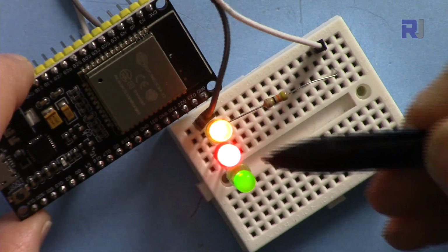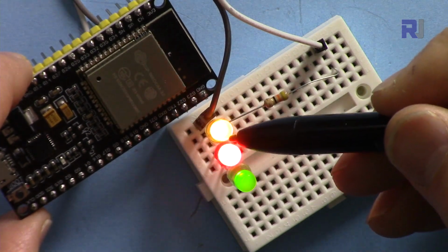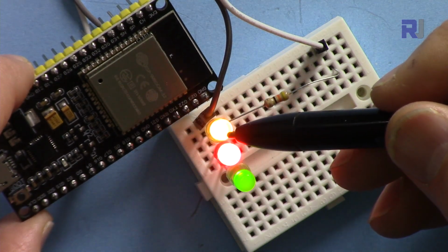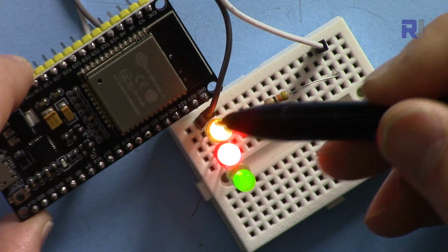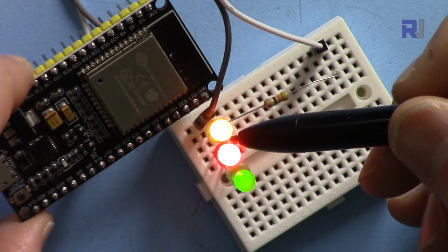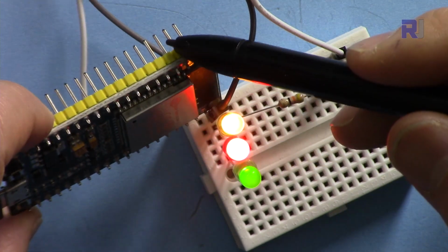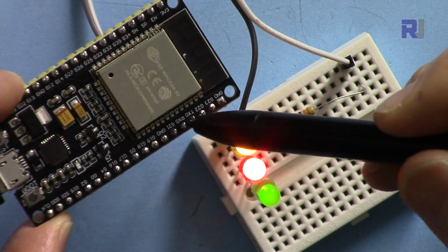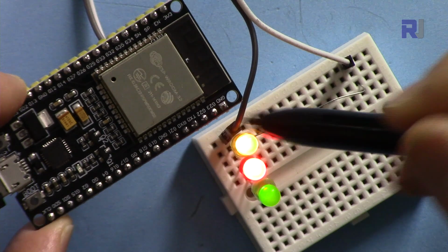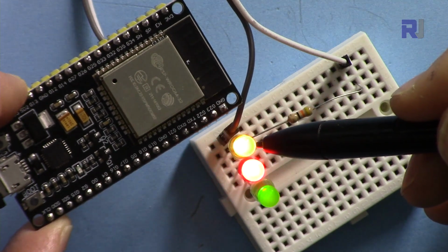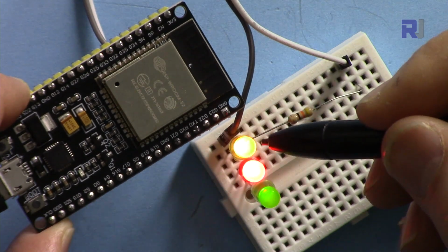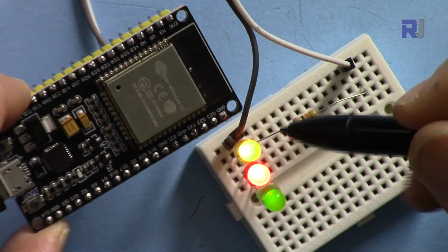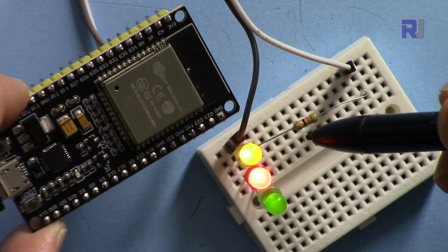Now each LED that you connect, depending on the characteristics, is generally about 2 volts, maybe 1.9 up to 2.1 volts, but on average we can say this is 2 volts, and the output from the ESP32 is always 3.3 volts. All these pins that are outputting are 3.3 volts. So if you connect an LED directly to 3.3 volts, it will get damaged. Sometimes immediately, sometimes within a few minutes or maximum an hour or so, they get damaged and burn. So you have to put a limiting resistor as a divider.